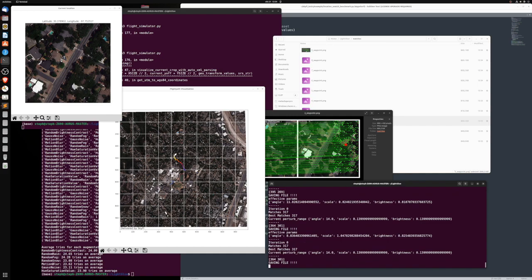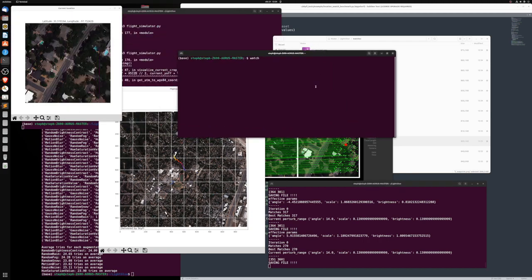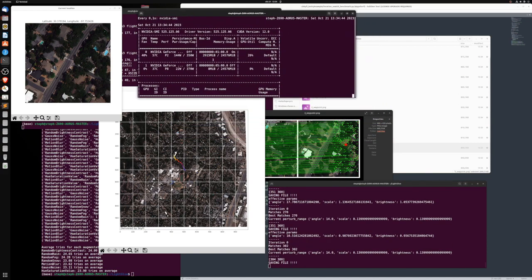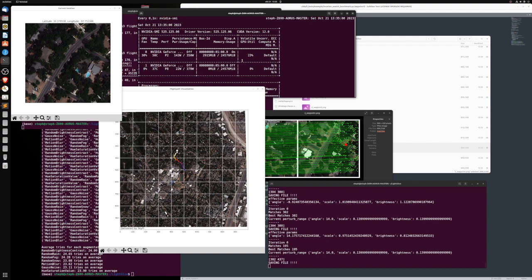It's like on this desktop machine, it's like 1/10 of a second. But it also actually doesn't use much resources. If we take a look here, this thing has a tendency to pop on top. Let's have a look at GPU usage. Here, as you can see, it sort of hovers around 3 to maximum 5 gigabytes of GPU usage, which means you could probably run this quite efficiently on a Jetson Orin or something that you can actually build into a relatively lightweight drone. My next thing I want to try actually is putting this on a Jetson Nano.